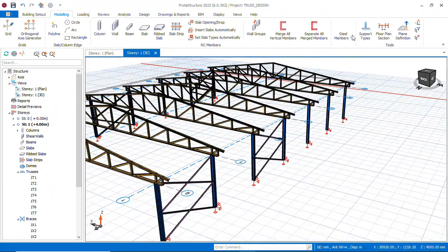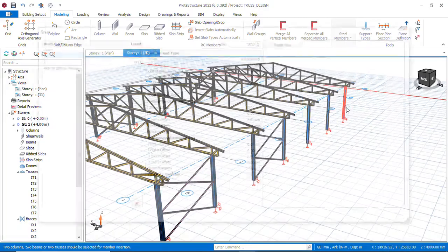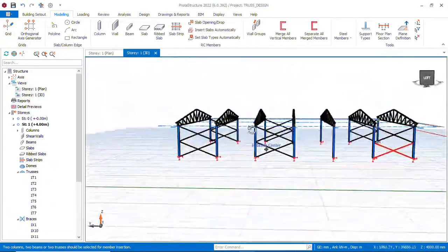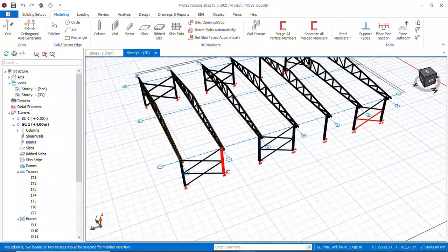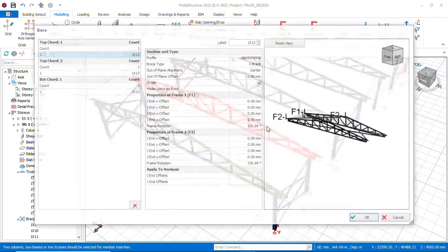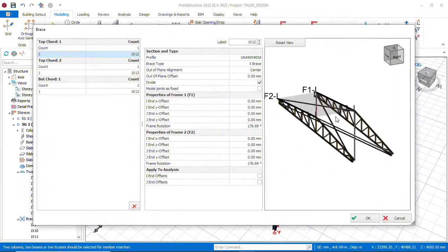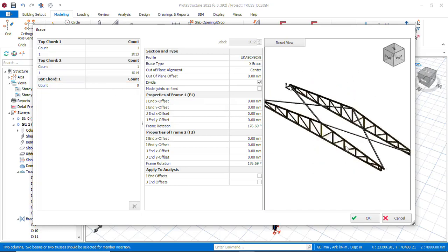You can see, do the same thing here to here. So this is how you put your, and then for the roof, you can click here to here. For your roof, you can see we have two types: braces up and braces down. So you can come to here. I only want my braces at the top chord and not at the bottom, so I can come here, remove this and say 0. So I can have only at the top.